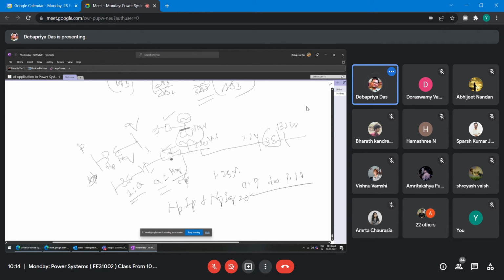That's why for load flow studies, when you are doing them in class, we are not teaching that, because things will become complex. Similarly here also, suppose you have a transformer. Here also you have a shunt branch. I can put the transformer shunt branch here, and another I can put in this bus. Whatever charging admittance there is, the shunt charging admittance, along with that this one will be added. That's why I didn't consider that.